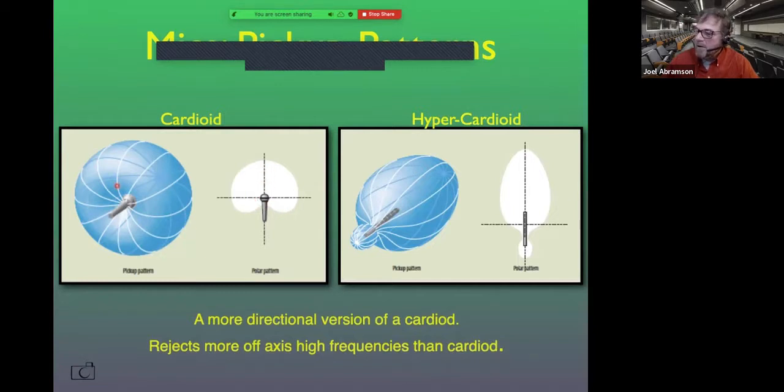Now this is a cardioid pickup pattern, right? But then we get into shotgun microphones. Even though the pickup pattern doesn't look like a cardioid pickup pattern, it is considered a cardioid because of the construction of the microphone, the electronics in the microphone. They mess with the electronics to take this pickup pattern and make it really longer out here, right?